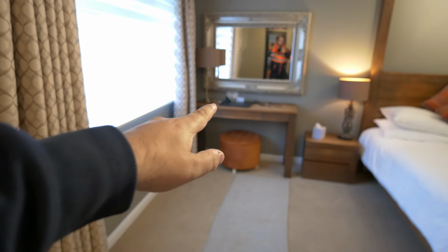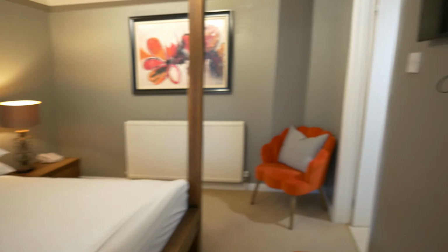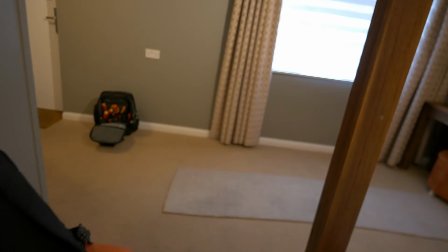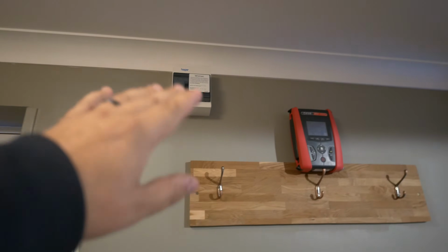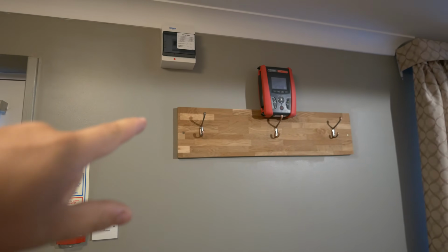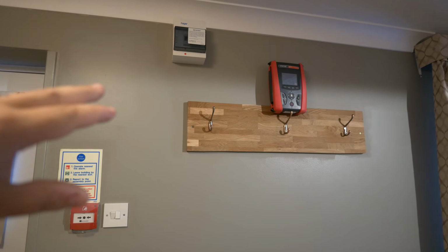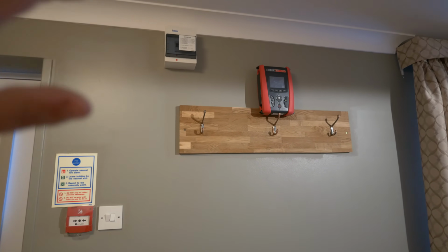And then with the power points, again, we knock the power off. You can see it's taken out that lamp. The rest of the equipment's all remained on. The TV's lost its power, and we'll determine the rest of that with our dead tests. So the next stage would really be to carry out some safe isolation, so we can isolate this board leading up to it. I can't show you that because it's in a public area of this premises, so I'm going to go and do that now.